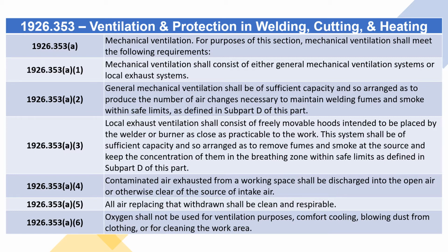A.4. Contaminated air exhausted from a working space shall be discharged into the open air or otherwise clear of the source of intake air. A.5. All air replacing that withdrawn shall be clean and respirable. A.6. Oxygen shall not be used for ventilation purposes, comfort cooling, blowing dust from clothing, or for cleaning the work area.